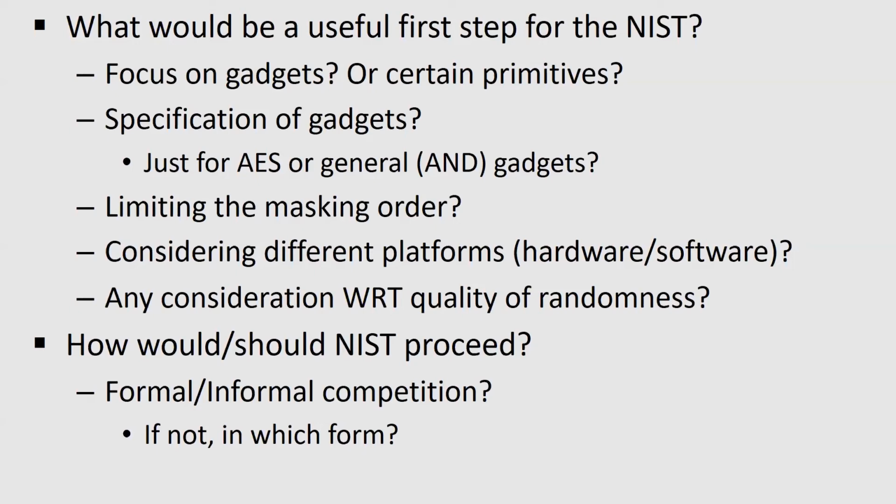I think the first question is, do we want to focus on an algorithm or a series of algorithms? Because then all the rest depends on that. If we want to be specific to the AES, of course, it calls for certain types of gadgets and S-boxes we will care about. If we want to be able to protect a few algorithms, it will call for different gadgets. And after this choice, I would be tempted to say we can do two things.